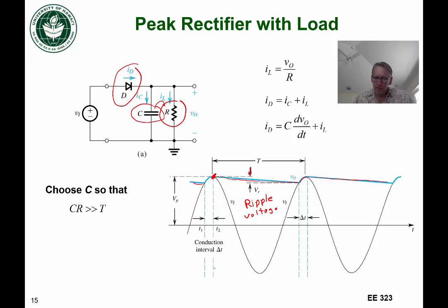And what we can see here is that during this time, the capacitor is charging through the diode. So the cap is charging. And then during this time here, the cap is discharging through R.